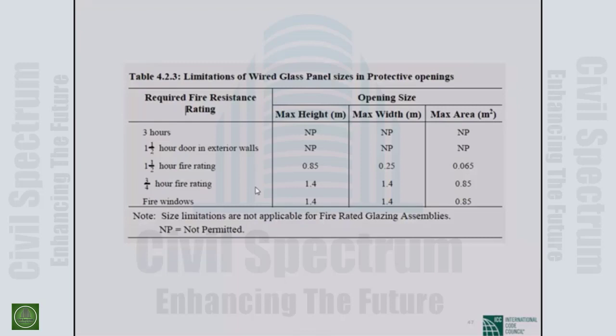So there is a very special type of fire rating of glass which is rated 2-hour, 3-hour, and in some cases very specially made glass is available rated 4-hour. Very expensive, very highly protected, but it is very difficult to make a fire rated glass. So normally a fire rated glass is one of a half-hour to 1.5-hour rating, and their size and